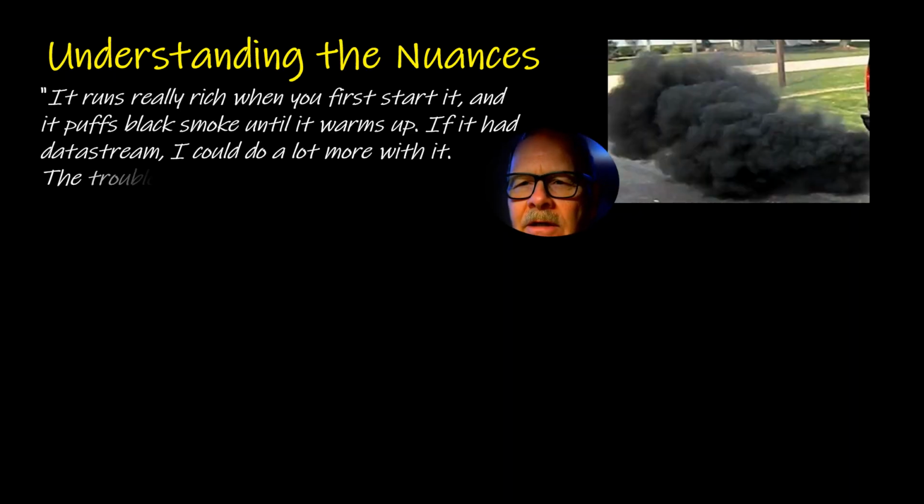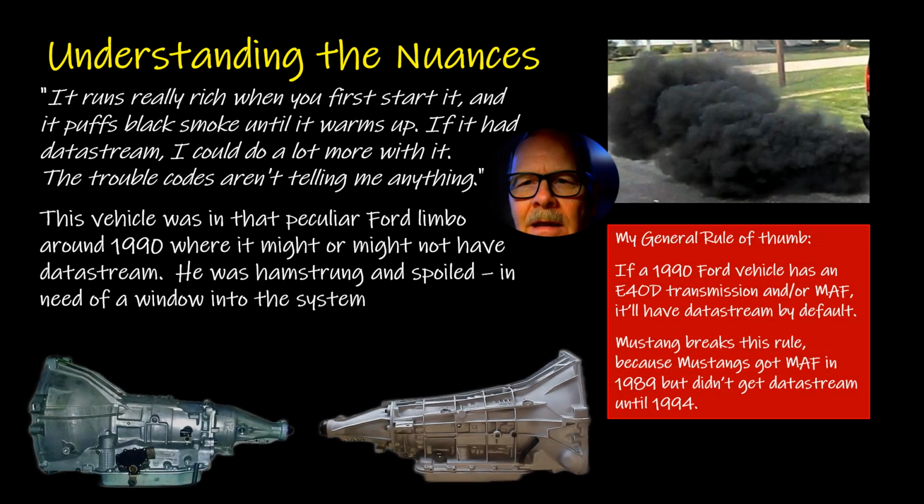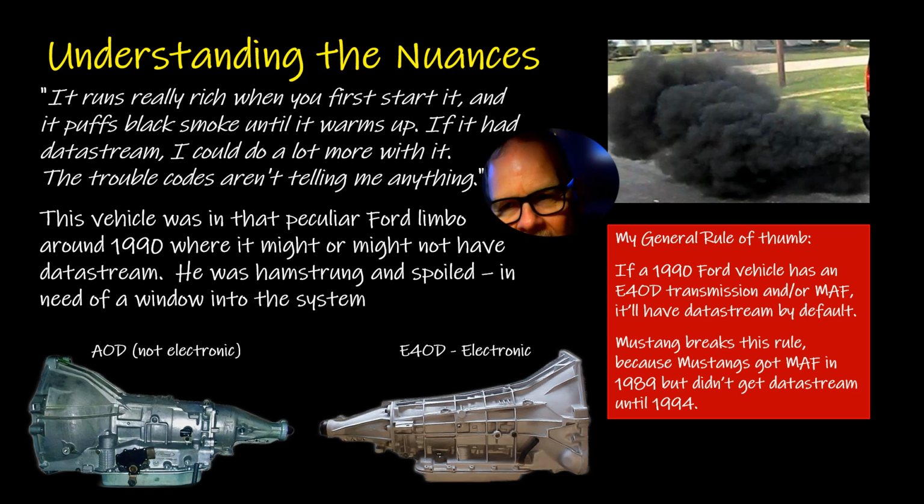And he says, it runs really rich when you first start it, puffs a lot of black smoke till it warms up. If it had data stream, he said, I could do more with it. The trouble codes aren't telling me anything. Well, this vehicle was in a peculiar limbo period around 1990 where it might have data stream and it might not.